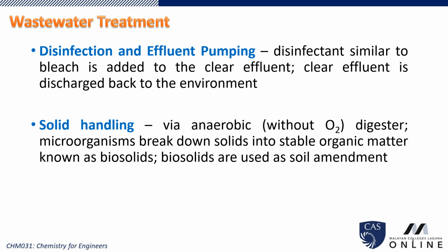For post-treatment and handling, disinfection involves adding chemicals such as chlorine to kill remaining pathogens before the discharge. For effluent pumping, the treated water is called effluent and is then released back into the environment. The solids produced during the treatment are called sludge, and the sludge is processed using anaerobic digestion, where microorganisms break it down into stable material called biosolids. These biosolids can be used as soil amendments, completing a resource recovery cycle.